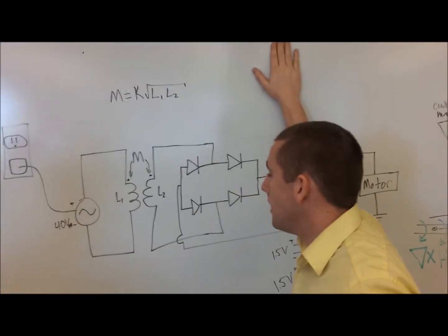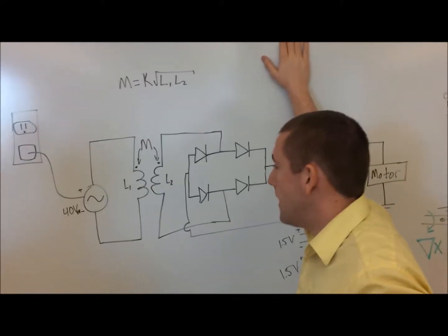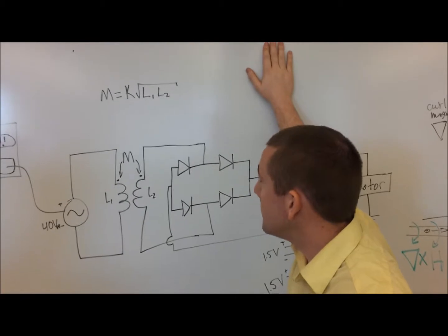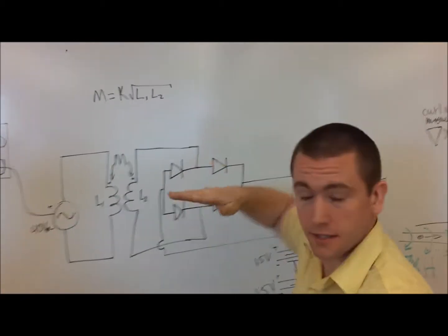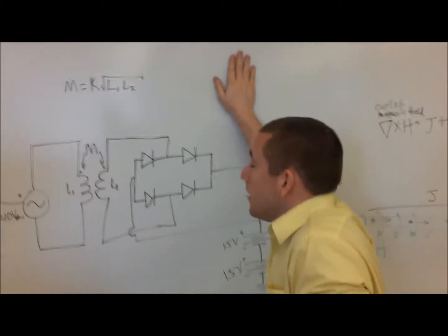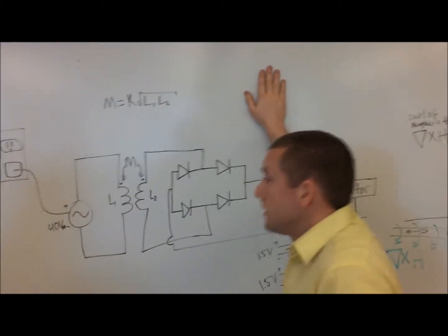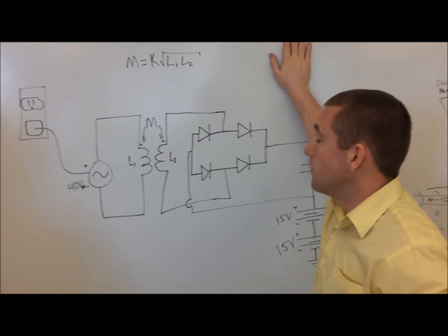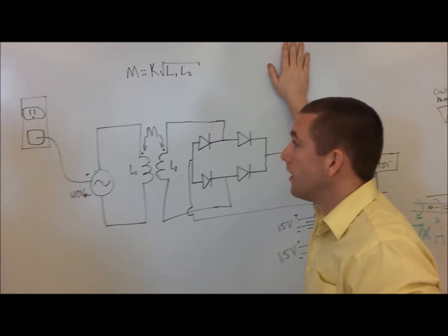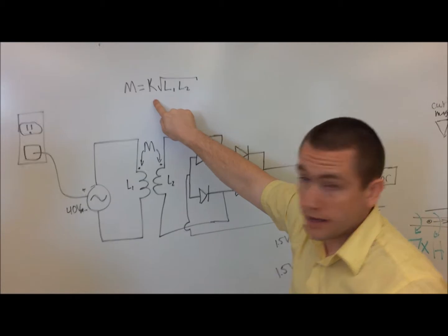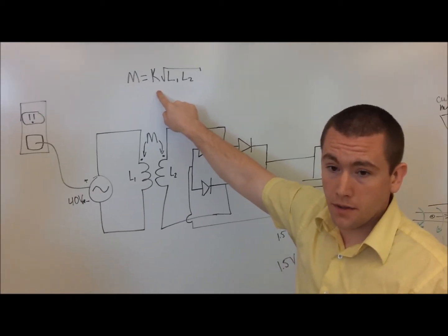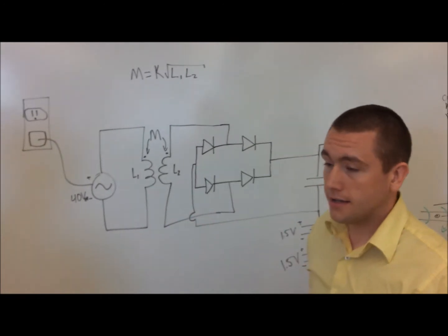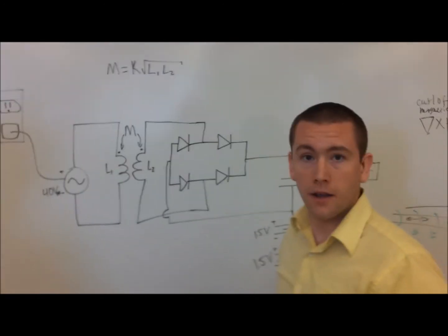and that has been the real challenge. We've done a lot of different things to maximize that by increasing or decreasing the distance between the two coils, and changing the size and the shape of the coils and the cores that they use. But with not sharing a common core, we're just having too much trouble keeping that value high. So the amount of power that's transferred from the primary to the secondary side is really tiny. Really tiny.